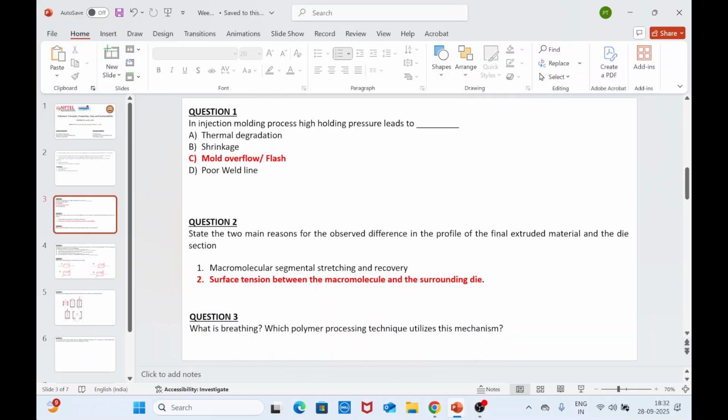If in case of a polymer what you actually want is mechanical strength, and out of the entire material, let's say 10 or 15 percent, or even 20-25 percent, is going to be occupied by voids, then that will not be very beneficial for mechanical strength. It will reduce the mechanical strength of the application or of the material.